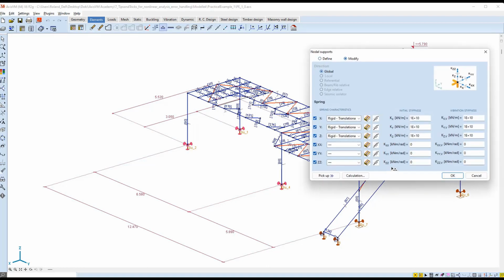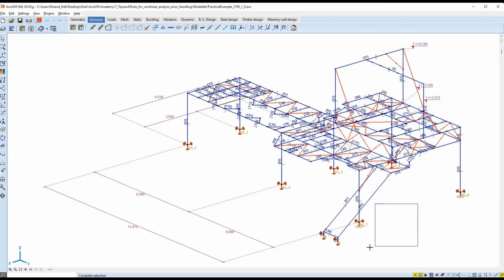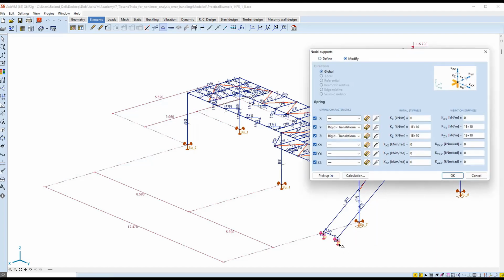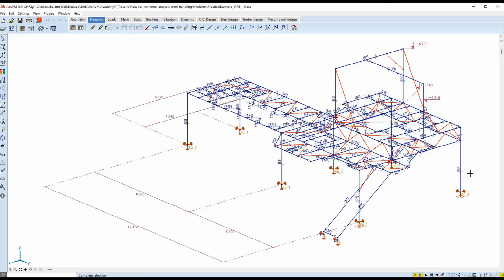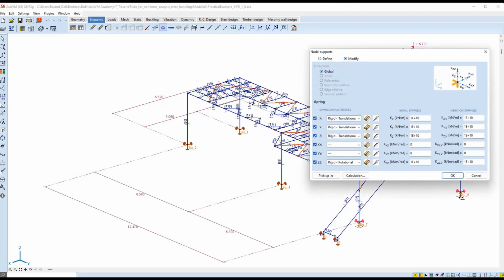The lower deck is supported by fully pinned columns. The ramp has pinned supports with free x-directional setting, and the supports of the columns at the side of the upper deck are pin supports as well, with restricted rotation around the global z-axis.